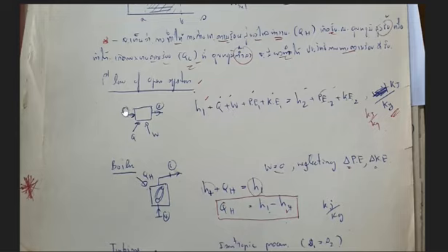So we have energy coming in, plus the heat that we put in or the work that we put in, plus the potential energy of the system and the kinetic energy of the system, will be equal to the energy of the water or steam coming out at state 2, plus the potential energy at state 2 and kinetic energy at state 2.